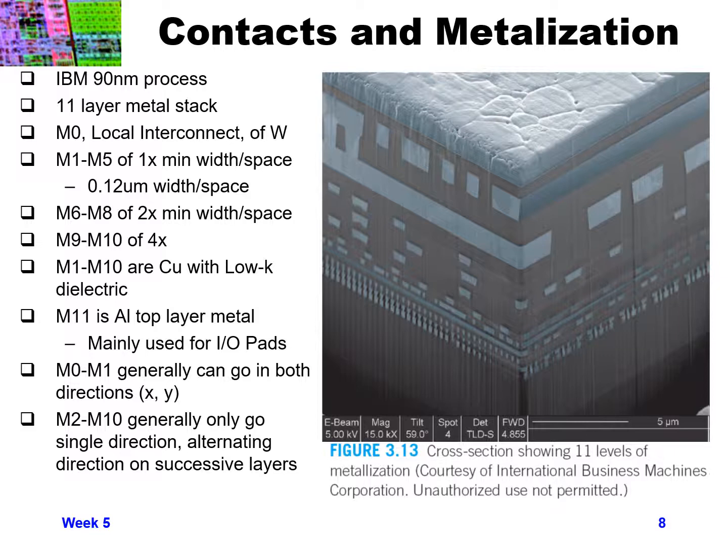So as we go forward in process technologies, adding more and more metal layers is one additional way of getting improvements. Again, it's nice from the standpoint that more metal layers give you better performance, but it adds more cost and potentially lowers your yield because it has additional processing steps.